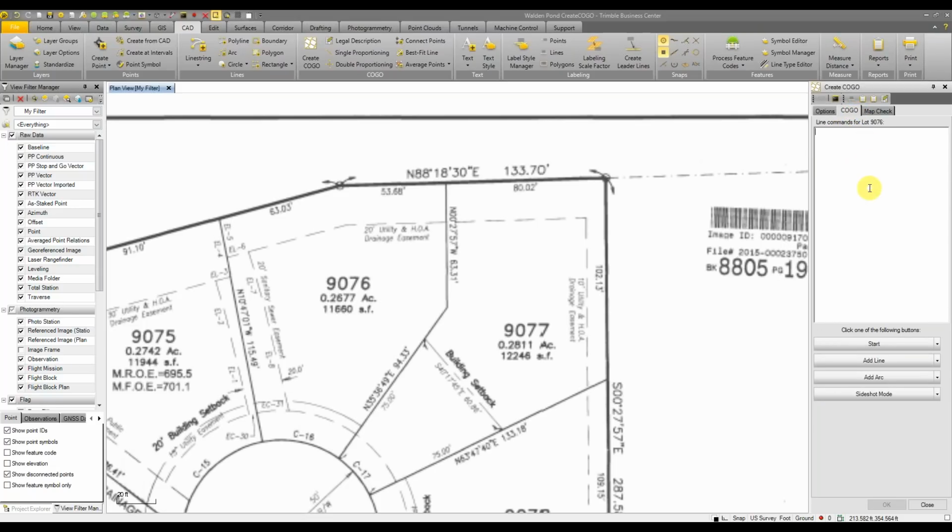So here we have the COGO window, big window waiting for you to type things. Scary, I know, but don't worry, it's not intimidating. You don't have to type if you don't want to. There are these 4 easy to use buttons down here. Start, that sounds like what we want to do. So we can start by coordinate, start by point, start by offset. These letters on the side, this is what you'd actually type in. So for start by coordinate, SC, it enters an SC up here.